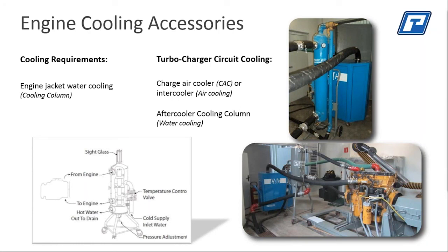The hot water is basically separated from the cold water, and further, typically the hot water side is 1/3 of the total volume of the reservoir. So the cold side is 2/3, the hot side is 1/3. Right. You do have that hole located in the bottom for the passage of the cool water to temper with the hot water, as I indicated. Does that answer the question? Yep. Thank you. Excellent. That's perfect.